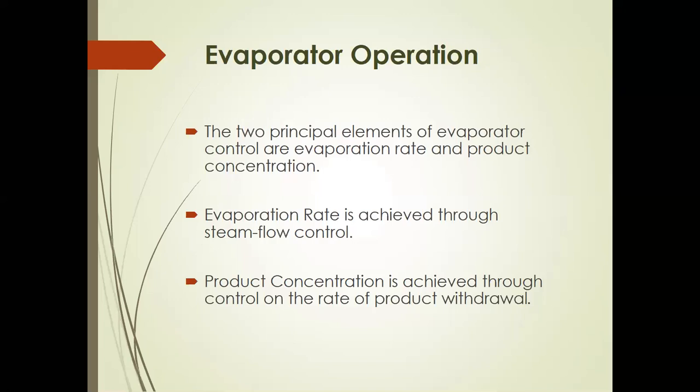Since it undergoes subsequent and prolonged evaporation, its concentration is enhanced. So the quality of the final product that is withdrawn is much better, or higher in concentration, compared to a particular evaporator wherein the feed only undergoes once-through evaporation.